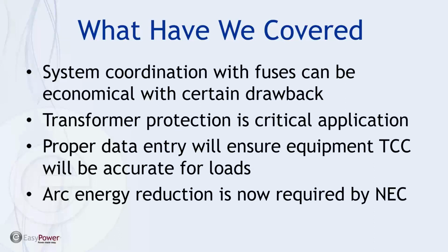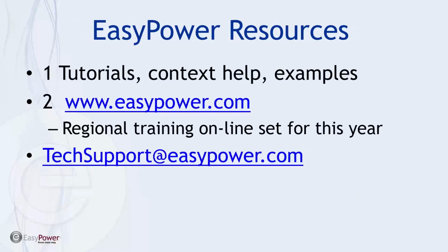It's very important, even more so, that proper data be entered during the modeling of the equipment so the TCC will be accurate for the loads. And in essence, whereas it wasn't the case before, arc energy reduction is now a requirement by the National Electrical Code.